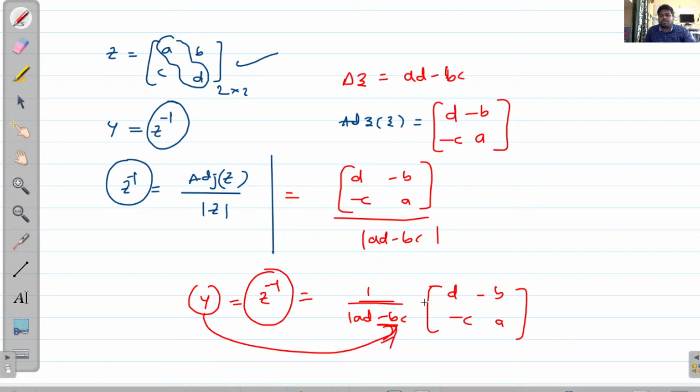You have two approaches: by converting T to pi (delta), then you can apply Y parameters directly. Otherwise you can find the Z parameters for a given T network. After that you can take the inverse of that matrix, and that will give the Y parameters. These are the two approaches, right? And next I will give one problem here.